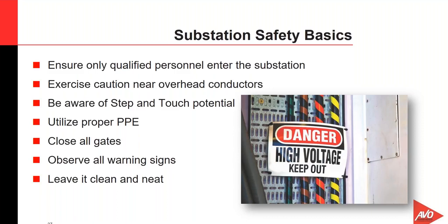Utilizing proper PPE is important. All these different substations are going to have different types of voltages in them, different types of incident energy levels, so we want to make sure that when we're doing work inside of these substations, we maintain the correct PPE, because it's for arc flash and arc blast.